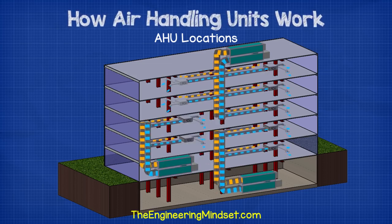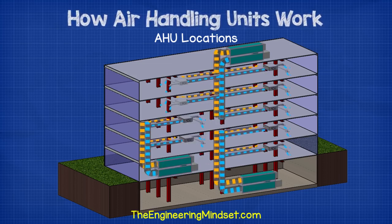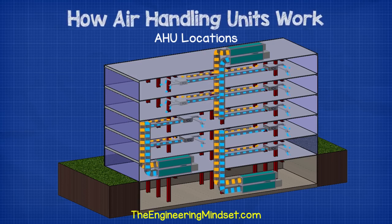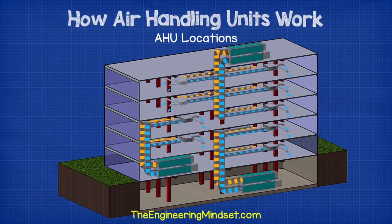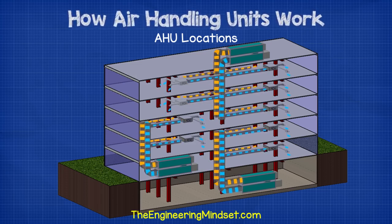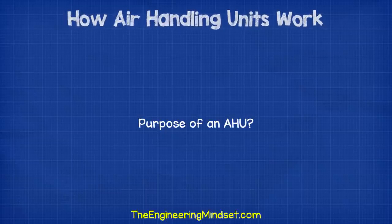Now it's most common to have multiple smaller AHUs supplying different zones to give better control and higher quality space conditioning. Buildings are now also much more airtight, so we need to have a return duct to regulate the pressure inside the building. So what is the purpose of an air handling unit?